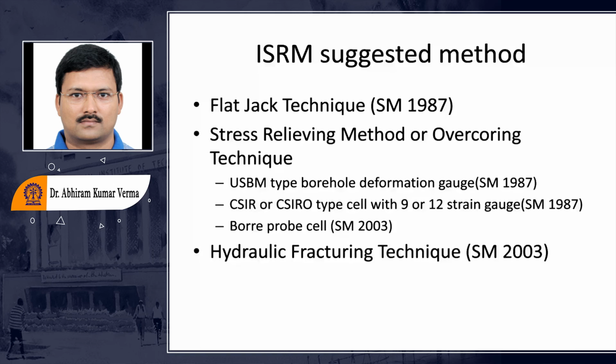Different methods have been developed over the years, but these five methods have been accepted all over the world for determining the in situ stresses. First method is the flat jack technique. Second is the stress relieving methods or overcoring techniques, and third is the hydraulic fracturing technique.